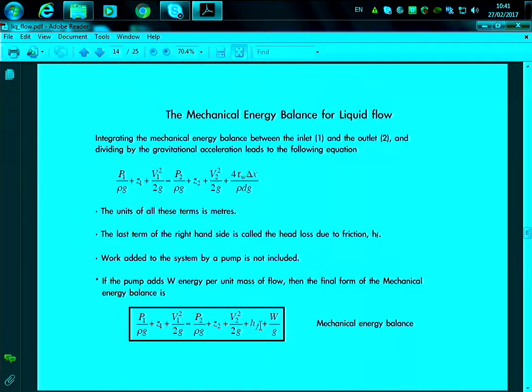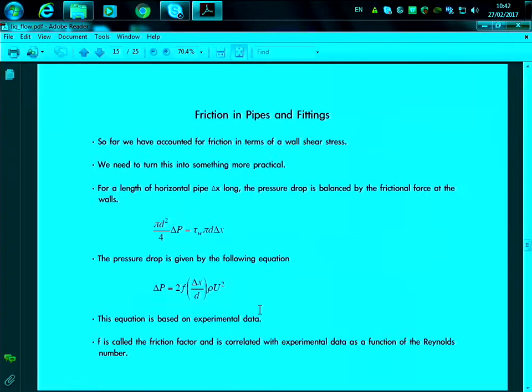We'll look at it as the pressure losses that occur due to friction, and in order to do that, we'll define the changes in pressure in the pipeline that occur due to friction. Sorry, I think this U should be velocity. Change that to V. That's velocity.